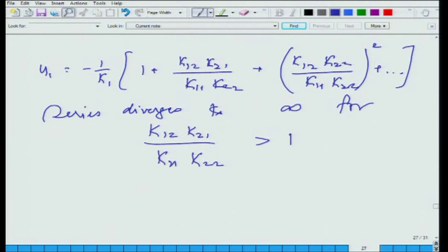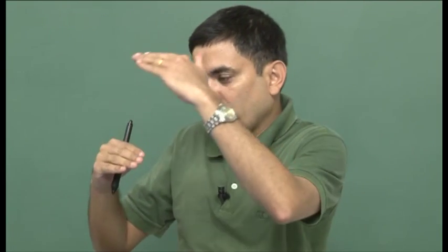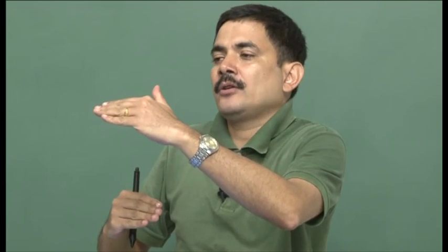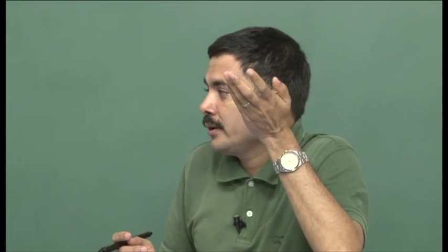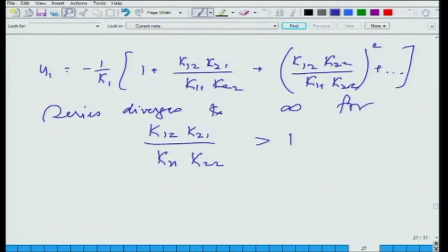All right. Therefore, if this condition is satisfied, guaranteed the interaction is so bad that if I am trying to maintain both y1 and y2 at set point, the inputs will blow up to infinity. u1 will blow up, u2 will blow up, to plus infinity or minus infinity.